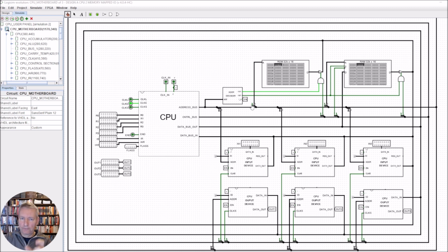So there's one of them got 15 bits, and then the second one has got the 16th bit, which we aren't using. Okay, so we pull out those 15 bits, and that gives us 2 to the power of 15, which is a 32K. And again, we do the same thing here for the RAM, and we pull that out, and we pull out the 32 kilobits. So that's basically the ROM and the RAM, and it's just the same as we had seen in the previous videos, but we've just changed the diagram round a little bit, just to make it a bit neater.